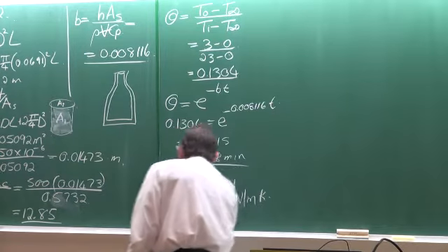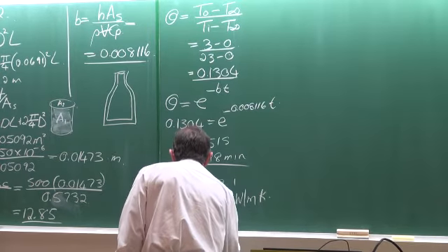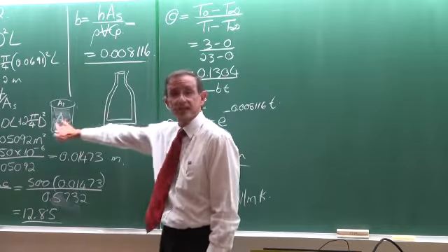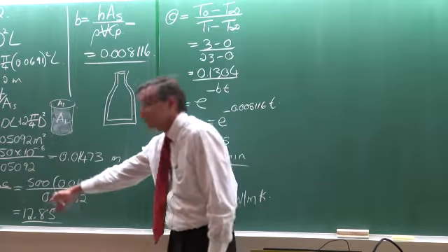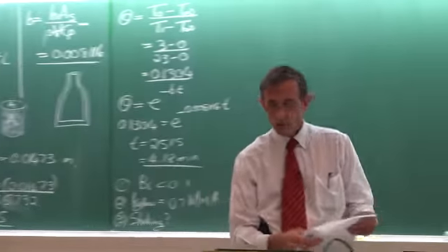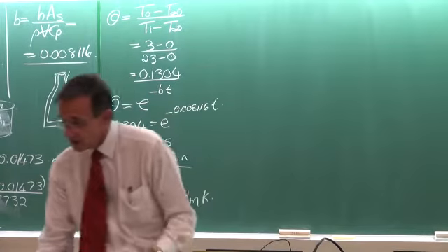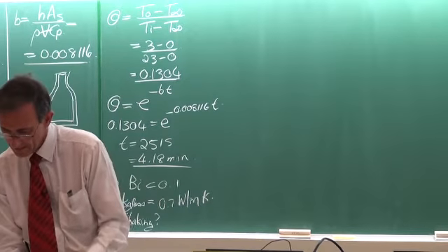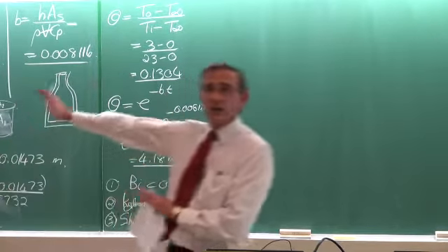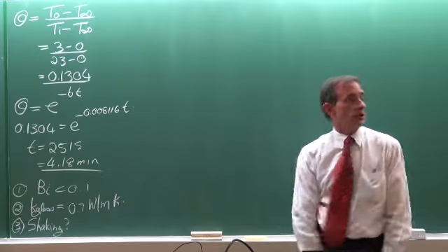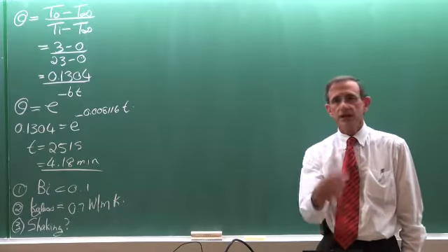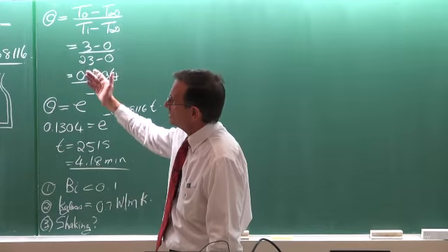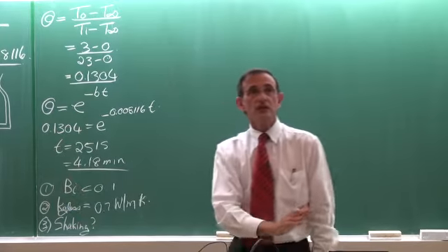Okay, so the shaking, we change the internal resistance on the inside to maybe a Biot number of smaller than 0.1, and then maybe that is possible. It can be done maybe then. Right, so that's a lump system approach in terms of the calculation of the time that it will take before the temperature decreases from 23 degrees Celsius to 0 degrees Celsius.